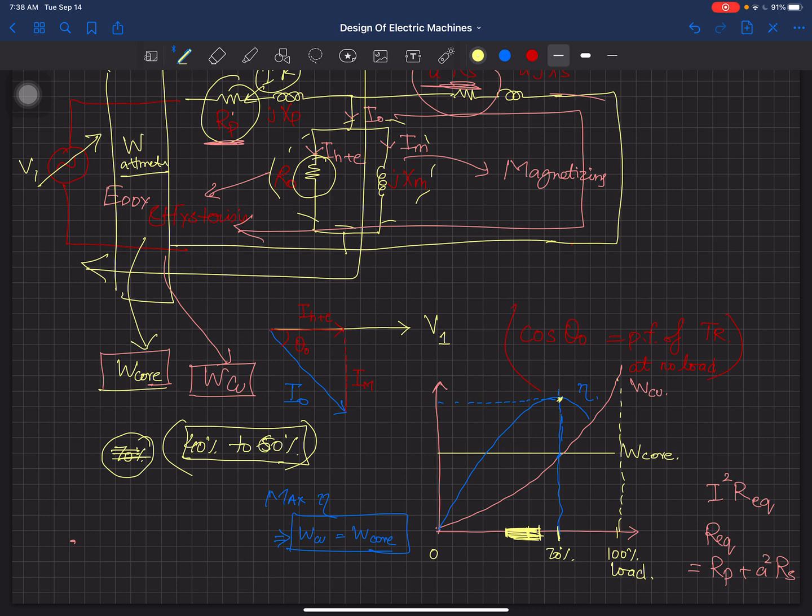But when you are going to design a power transformer, you are going to make this curve more shifted towards the full load side, because the power transformer, when it is working, it's supplying the power from the generator, and that generator is working at almost the full power. So you have to have it designed for maximum efficiency there also. So this is design work for the designer, how you are going to get that design done, so that the losses are certainly in the designer's control. We will design it and you will understand this a lot.